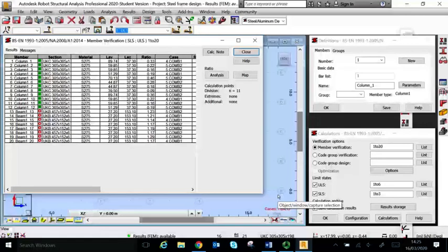So we need to increase the beams even more. They're failing slightly, so the factors are quite close to 1. However, some of our columns are really not utilized now. So, perhaps we could reduce the columns a little bit